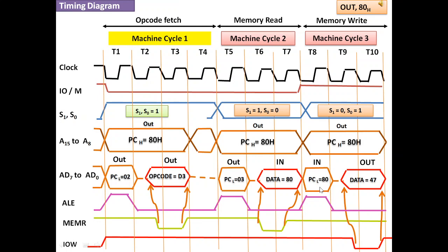For the simplicity of decoding, the manufacturers have created the microprocessor in such a manner that whenever an OUT instruction is executed, the upper address bus also carries the same physical address as the lower order address bus. So the system and board manufacturers can decide which one to use for decoding purposes.